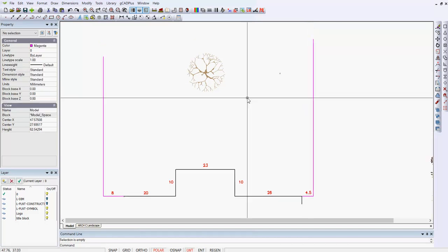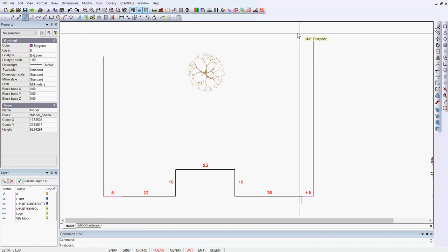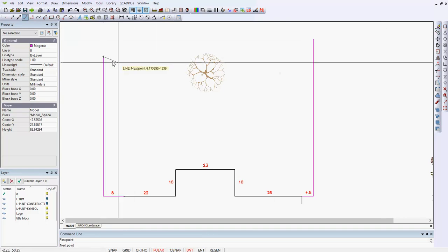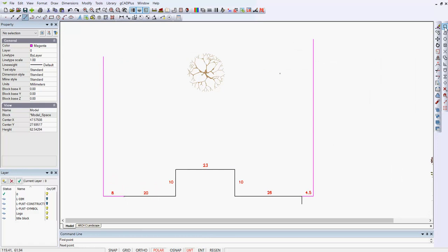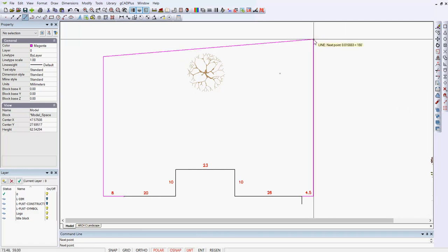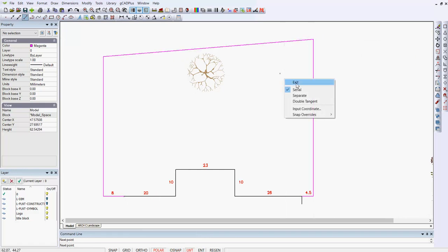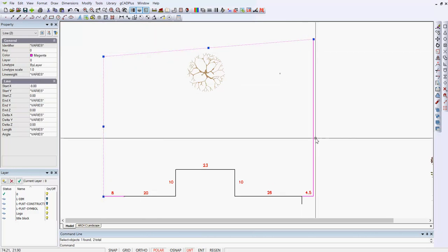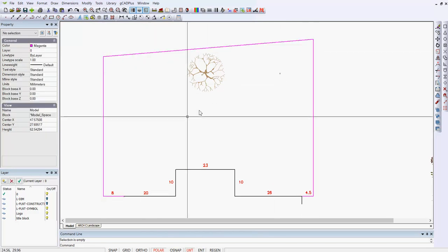We now need to draw in the back boundary, which clearly slopes. This time I'll use the line tool on the Draw 2D toolbar, pick line, and although earlier I had floated the toolbar for entity snaps, I've moved it off to the side, and I'm going to snap to the end of that line, come across to the toolbar again and snap to the end of that one, right click to exit. Now those 3 lines constitute the boundaries of the rear of this property.